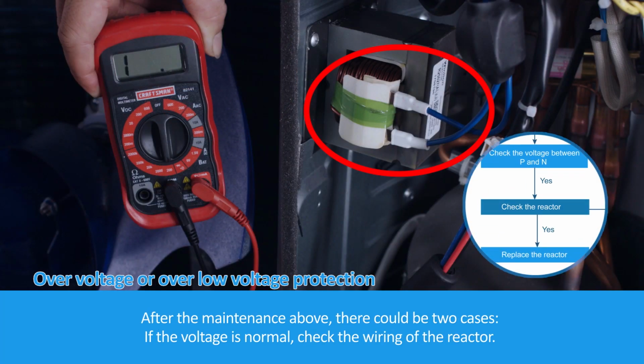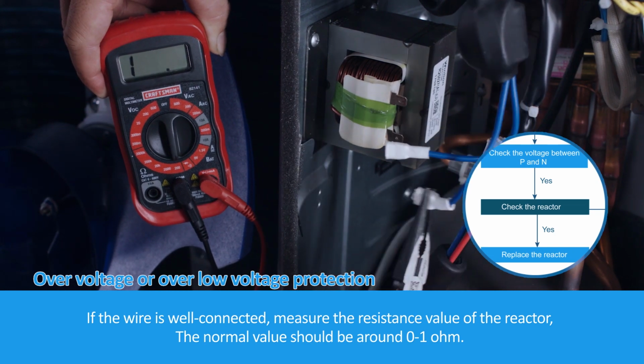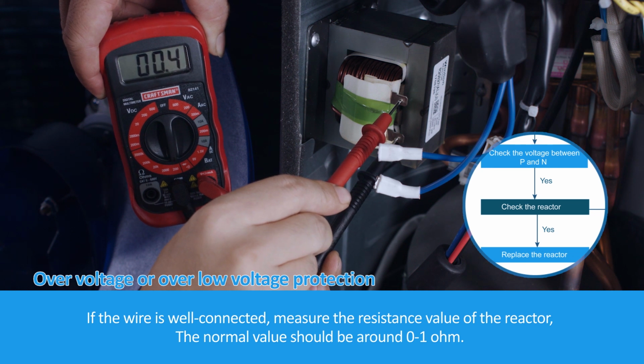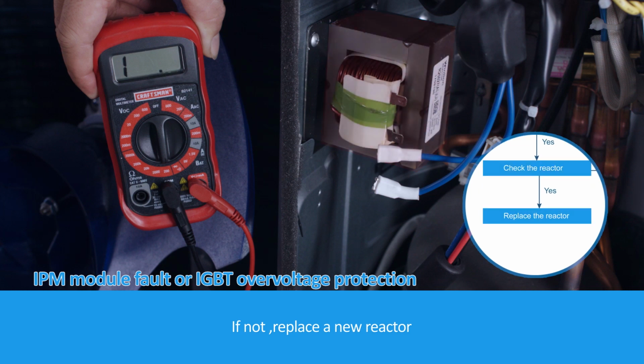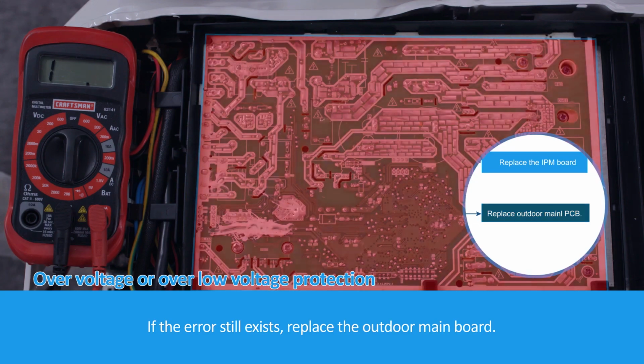After the maintenance above, there could be two cases. If the voltage is normal, check the wiring of the reactor. If the wire is well connected, measure the resistance value of the reactor. The normal value should be around 0 to 1 ohm. If not, replace with a new reactor. If the error still exists, replace the outdoor main board.